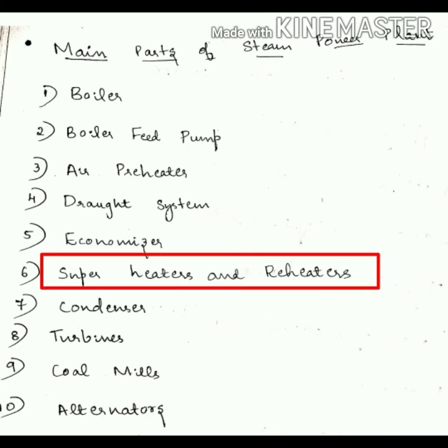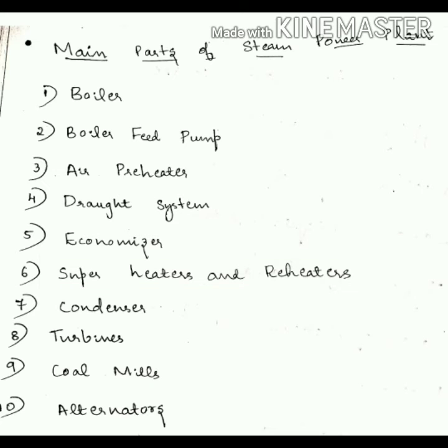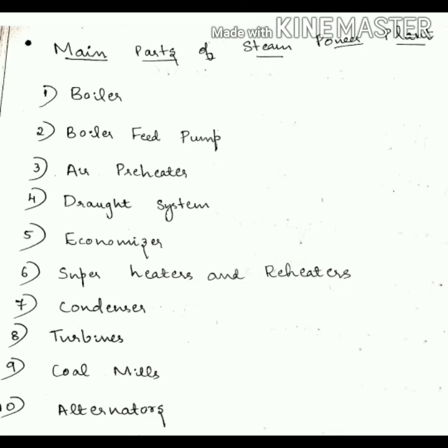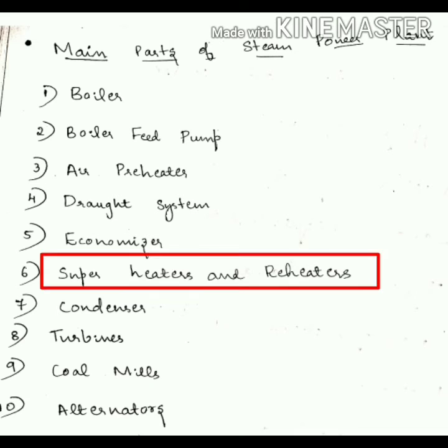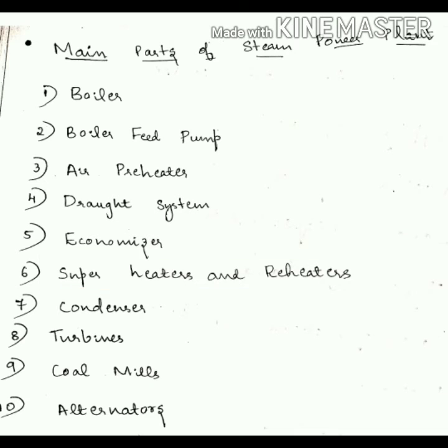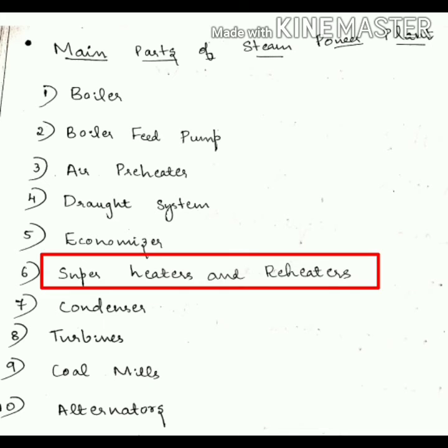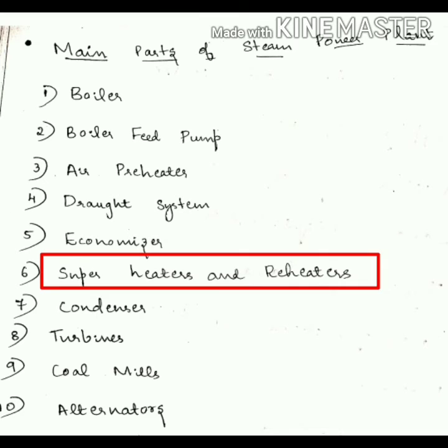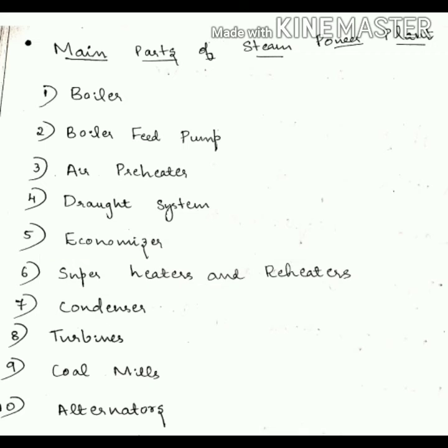So where can you see a superheater? You can see that superheater is placed just before a turbine and after the boiler. So we know from the boiler, anyways, a high pressure and temperature steam is produced. But this is not just sufficient to increase the overall efficiency. What we can do is we can further pass this steam to a superheater before giving it to the turbine.